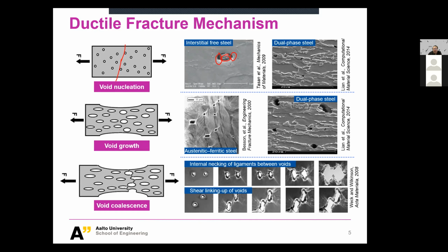So these are two voids already. If you just continue that, they will become round and they will grow. So they become really a big void. And finally, you will see from the metallography figure, the void is becoming that big and you have this kind of cute inclusion inside. So this is one very typical behavior for clean materials or single phase material.